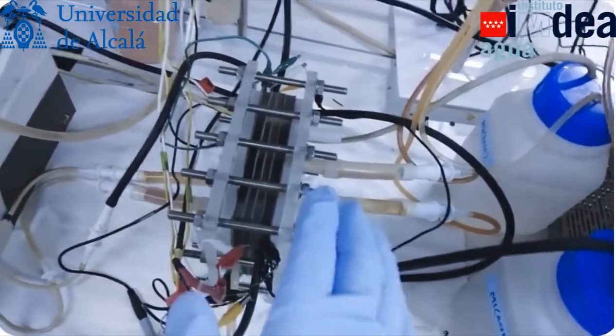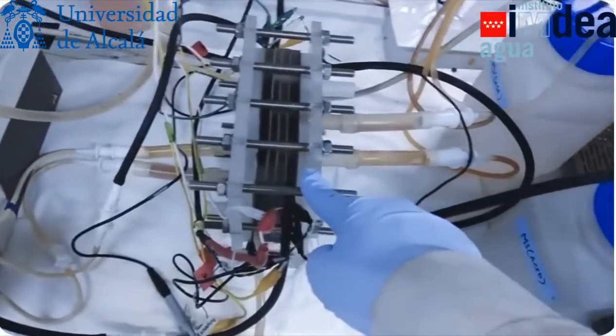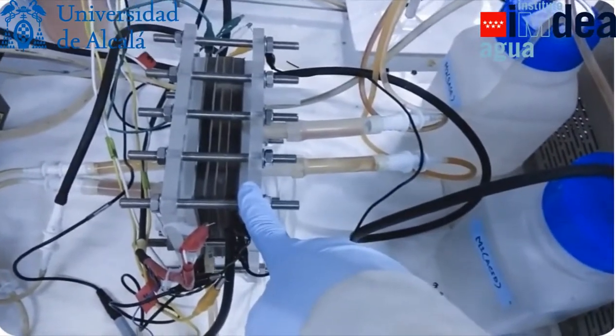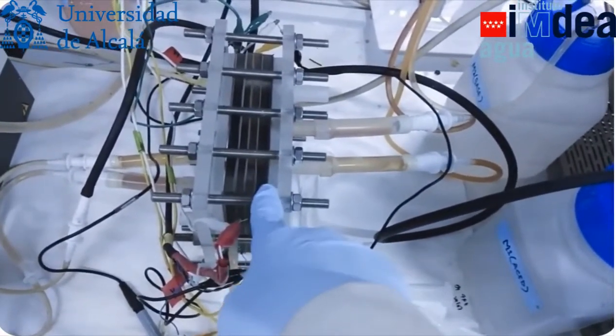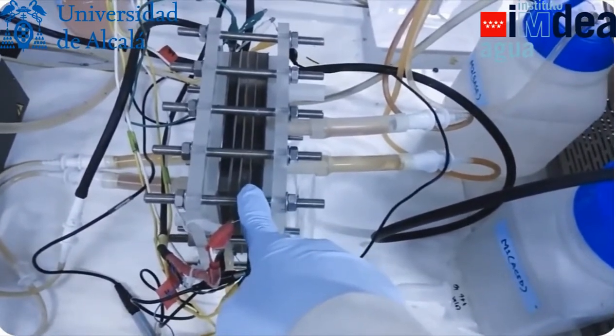After getting sufficiently treated, the wastewater comes to this holding tank, and from this holding tank it goes to the anode chamber. In the anode chamber, bacteria present at the anode degrade organic matter into CO2, H+ and electrons, and at the same time the leftover cations migrate from the anode chamber to chamber B through this cation exchange membrane.